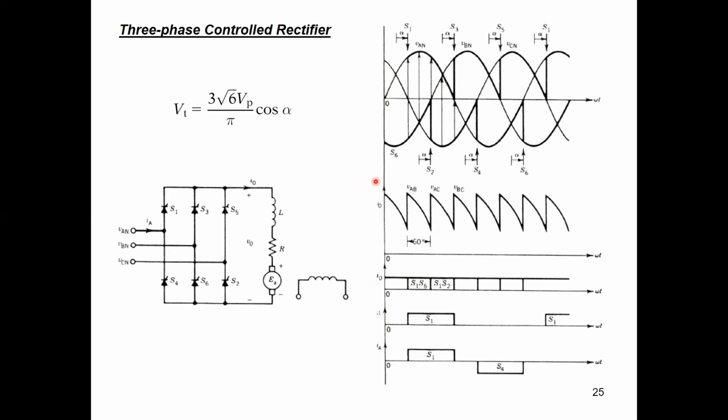We just have to understand that we have a 3-phase controlled rectifier, and the output of the 3-phase controlled rectifier during one complete AC cycle, from 0 up to 2 pi, will have 6 peaks, if you count with me, 1, 2, 3, 4, 5, 6. So we have 6 peaks, and the firing angle alpha starts from the reference of this point.